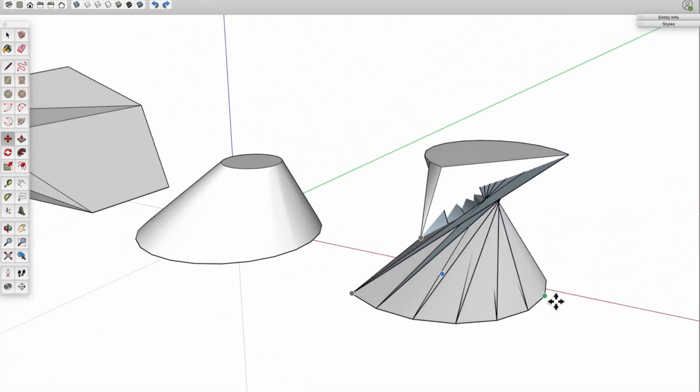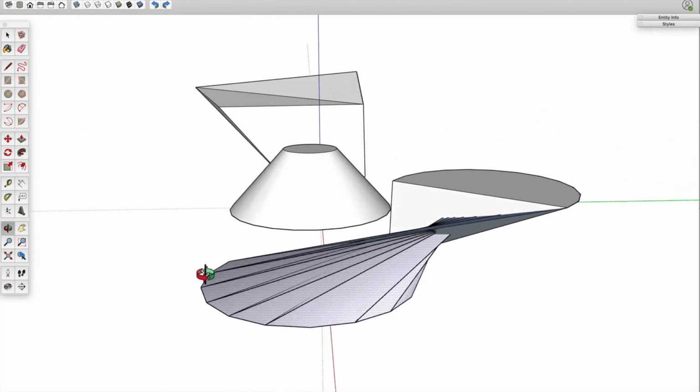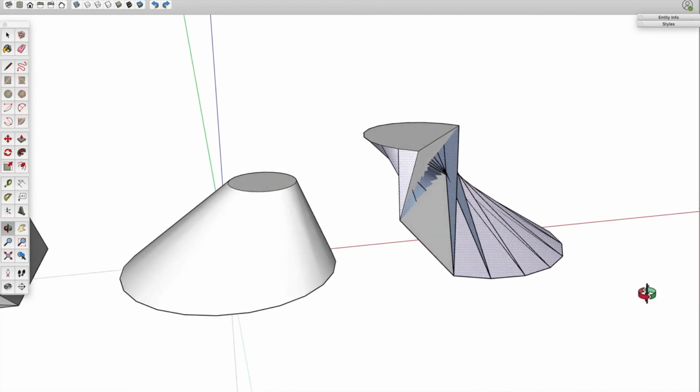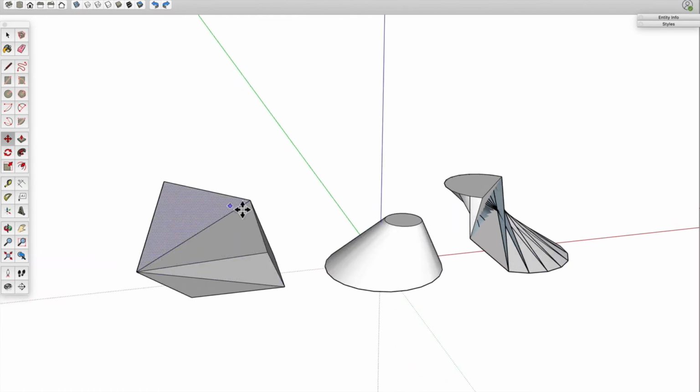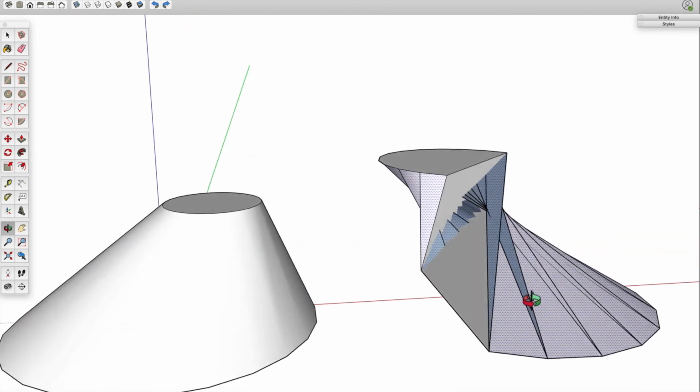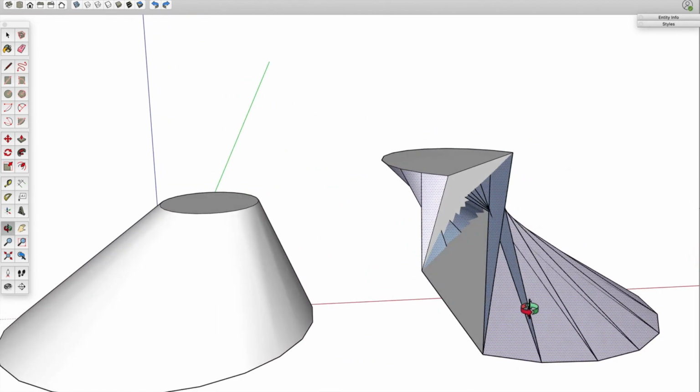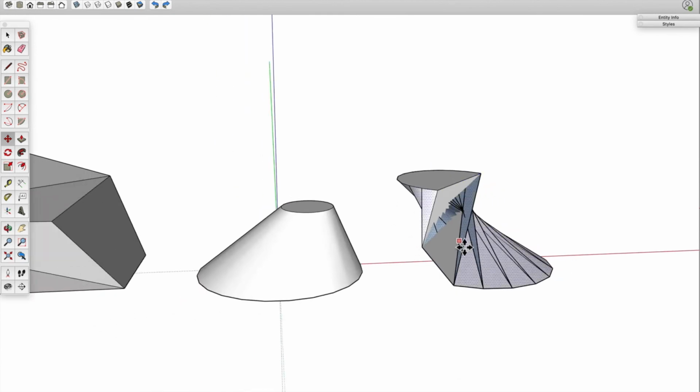And you'll see this is why SketchUp locks down the ability to autofold sometimes by default. This shape right here, maybe you wanted to do this, but if you didn't, you really got it all twisted up pretty fast. Whereas on the other shape, it was able to build in some autofold lines pretty easily, so it didn't lock us down originally. So it's a nice feature to be able to unlock, but you also have to be careful.